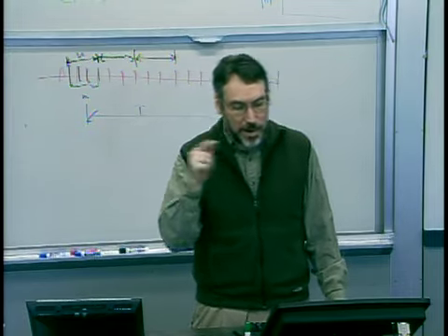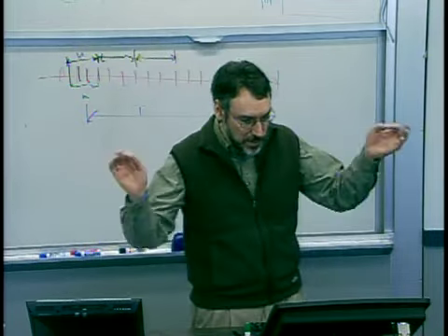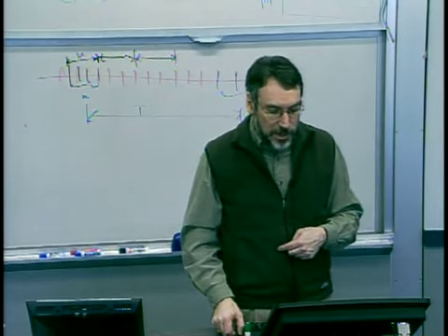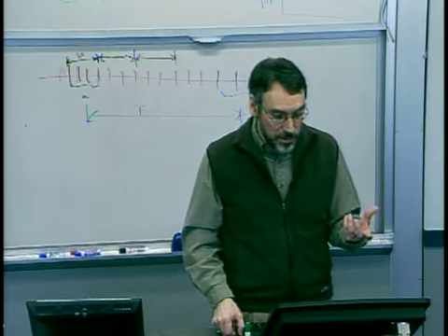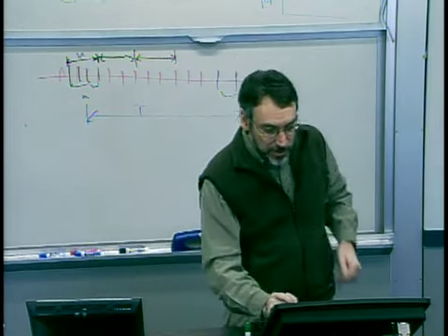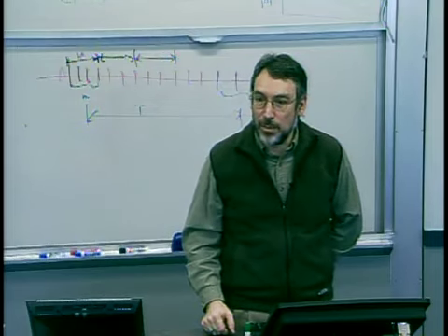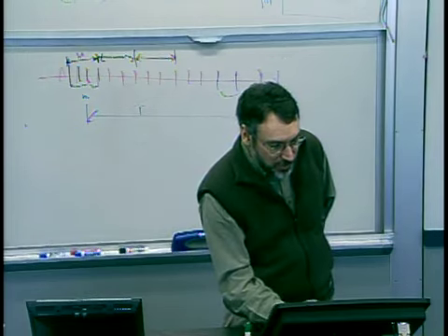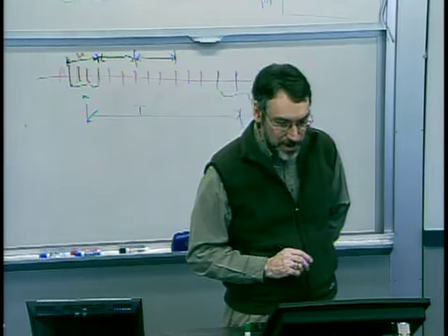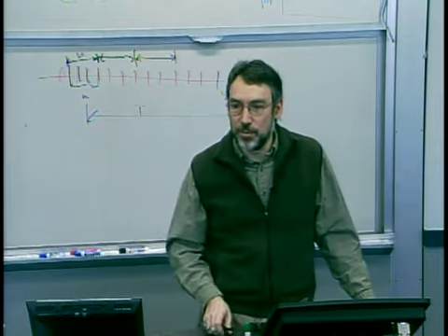In fact, you can ask upper spec limit, lower spec limit. We actually know the number much more carefully. It's really 3 out of 1,000, those probabilities. If I go to a CPK of about 1.33, that corresponds roughly to a Z of 4. 4 sigmas. I'm 4 sigmas away from the spec limit. You can see I get about 100x reduction in the number of non-conforming parts. If I can go another standard deviation, or a CPK of about 1.67, I get another factor of 100. And similarly, I get about another factor of 100 if I can get to a CPK of 2.